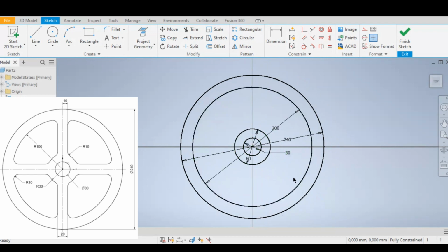If in fact you did select a parameter that is not correct, you can simply double tap on this dimension and you can change your dimension from there. So it's a quick and easy way. Once you draw something and you realize you have entered the wrong dimensions, you can then just revert back to your drawing and double click on your dimension to change it.